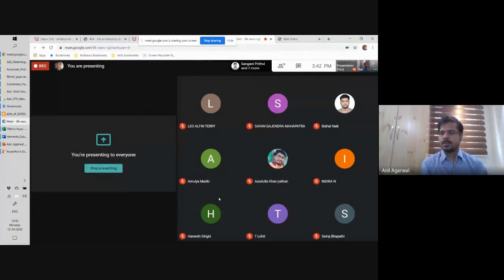In that entire design process, it seems so simple, but did we consider any loads here? I just looked at whether it's a beam or a column, and what kind of structure it is a part of. I never considered any loads on the beam. I never considered any boundary conditions of the beam. Correct? Typically, we are all structural engineers. We itch for that information, right? It seems so absurd that we never considered the loads acting on the beam, and we designed the fire safety of the beam.